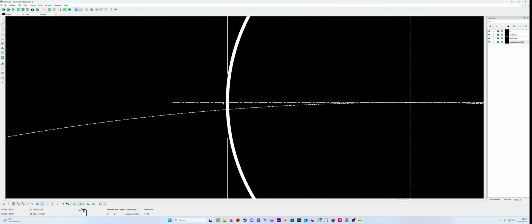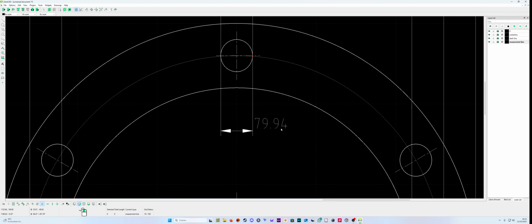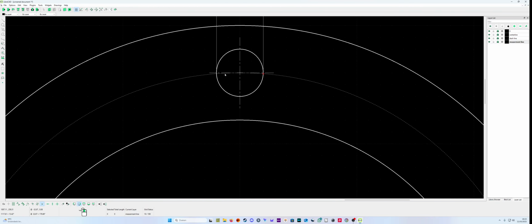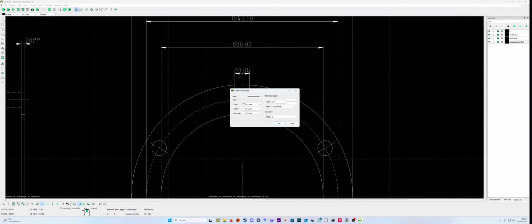This is the real center line, and I measured here, and that's this 0.06 difference. So always be careful where you measure, guys. So it's good that it happened, so I can show you what was wrong. But the holes are 80. That's the real measurement. Let's say 80 H7.